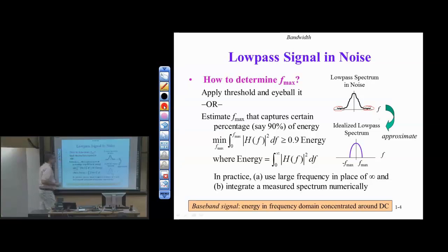All right. So the noise here is really more or less flat over all frequencies. But where the signal has more power than the noise, you're going to see it as really just squiggles along the spectrum. It's additive. I have some signal spectrum, and I'm adding to that this noise spectrum. Signal plus noise is what I'm really looking at. And I'll see the noise where the signal power is weak, and I'll see mostly signal where the noise power is weak relative to signal power.